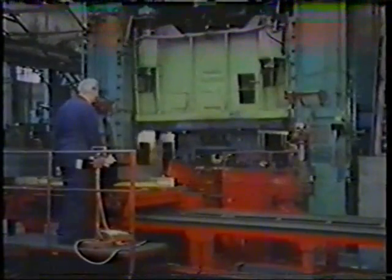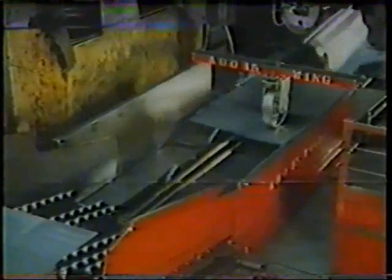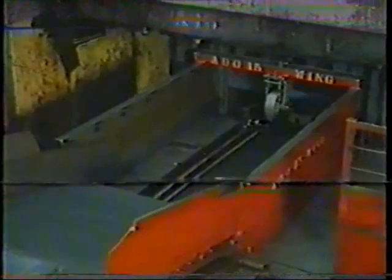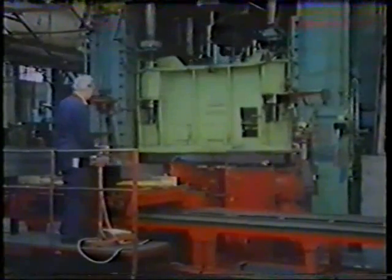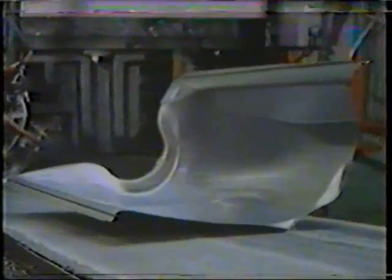Now, in many manufacturing processes, we need to be able to bend sheet steel. The body panels of cars are made by pressing out sheet steel in a huge hydraulic press. For this process, the steel needs to be relatively soft and ductile. So, after cold rolling, the properties of the steel must be changed. We do this by heat treatment. It's a process known as annealing.